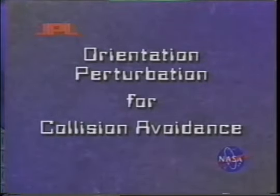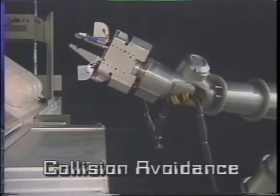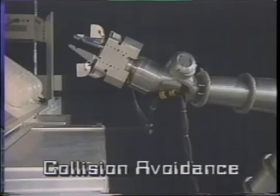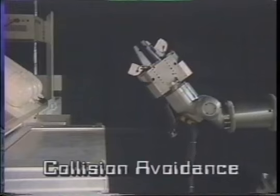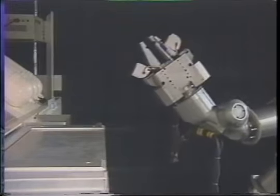This experiment illustrates orientation perturbation for avoidance of a near collision between the wrist of the right arm and the top edge of a rectangular box in the workspace. If the obstacle is closer to the wrist than a preset distance, the end effector orientation is perturbed automatically to rotate the wrist away from the obstacle while maintaining the commanded position trajectory.